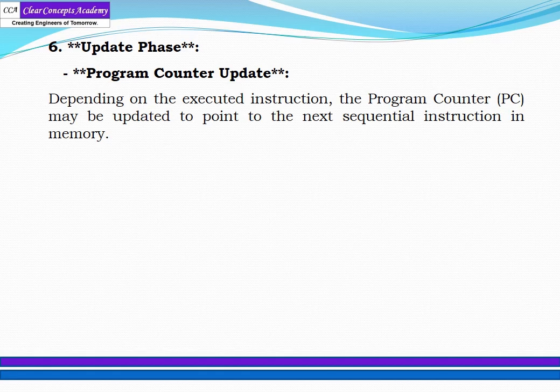Say a return command is given, or subroutine execution is there. Suppose the program is running and in the sequence a subroutine call comes, go to this place. After executing that subroutine, when the return command in that subroutine is executed, it has to come back to the program from where it jumped.